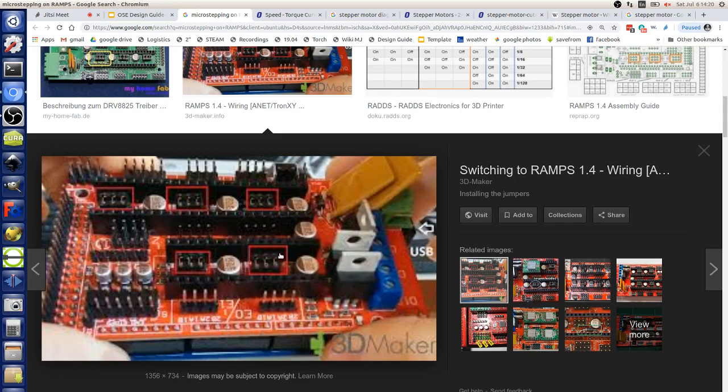at varying time intervals when you have micro-stepping. There's a little microprocessor on board each of these stepper drivers, which allows you to do just that. So you don't just plug a stepper motor into the wall, you give it a finely controlled pulse sequence, and that pulse sequence is controlled by Marlin. Marlin gives the stepper drivers basically step, direction, and enable signals. And how do you control the speed? You control it by how fast you're switching the poles.